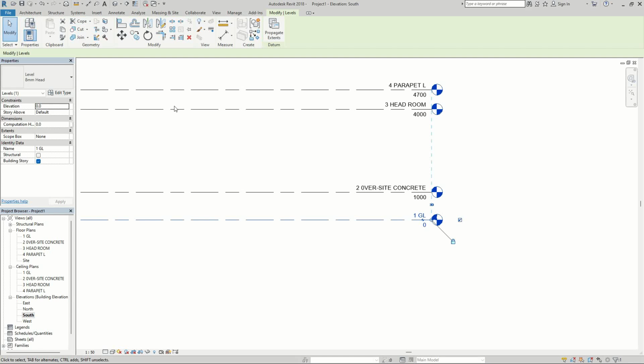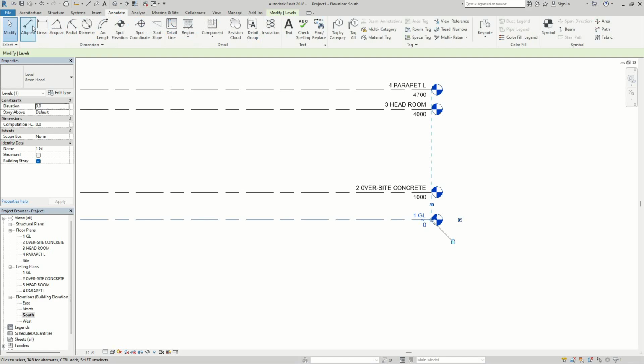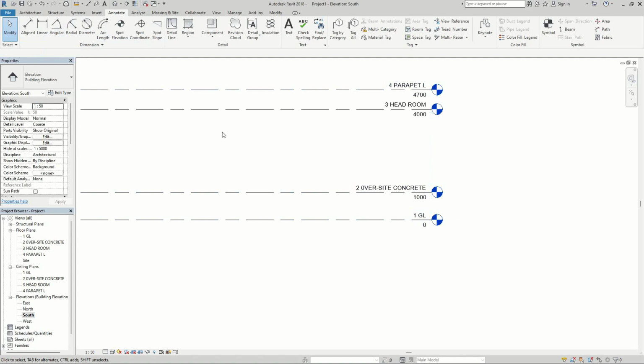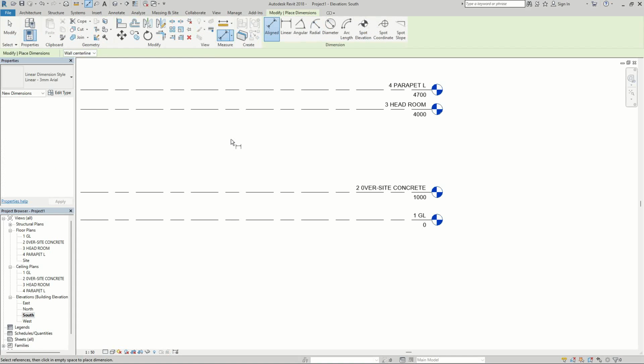To initiate this dimension, whenever you select an item, let me go to annotation. Here in annotation, I can pick the dimension now. But how we initiate dimension is with the command prompt function DI. With DI at the first instance, you initiate the dimension, and same is selecting the alignment.